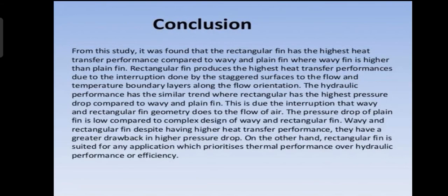Conclusion. From this study, it was found that the rectangular fin has the highest heat transfer performance compared to the wavy and plane fin, where wavy fin is higher than plane fin. Rectangular fin produces the highest heat transfer performance due to the interruption done by the staggered surfaces to the flow and temperature boundary layers along the flow orientation.